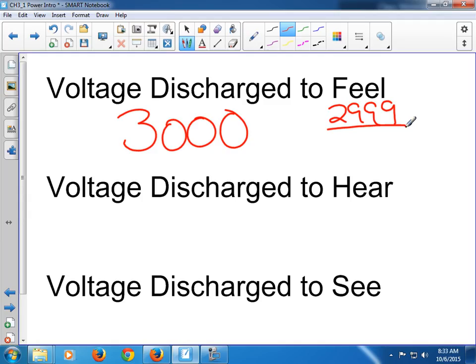That's why when students just start coming in and grabbing stuff, I'm like, ah! Okay? Because they can easily ground themselves to that component by discharging into something that's fragile. Which is why we always touch the metal case, we always touch the power supply before we touch anything else inside a computer. A lot of computers don't have metal cases, that one does. A lot of them have plastic cases. You can't ground yourself on plastic, so you have to actually touch the metal part of the power supply.